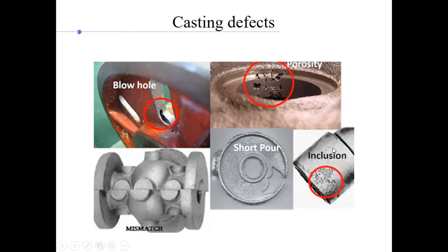When we are calling this aluminum, when it was made of aluminum, you have certain properties of aluminum that we know. But if these inclusions are there, they will act as stress concentration zones, and therefore that will be a design failure. You cannot take this into account, so that is to be avoided. Inclusion is one kind of defect. Is it clear?